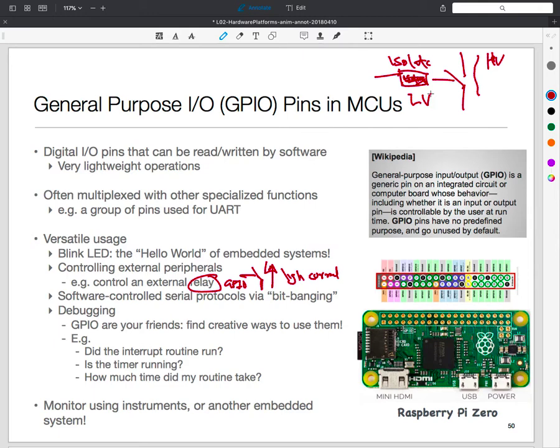On a standard computer, you have debuggers where you can pause and look at things. Here, you could do that, but a lot easier is simply to put these cheap GPIO instructions at the right places and monitor the pins. Put it onto a scope, put it onto a logic analyzer, or even use a second embed to just monitor the first embed, right? Because using the GPIO on the second embed, you can create your own fake instrument for this purpose.